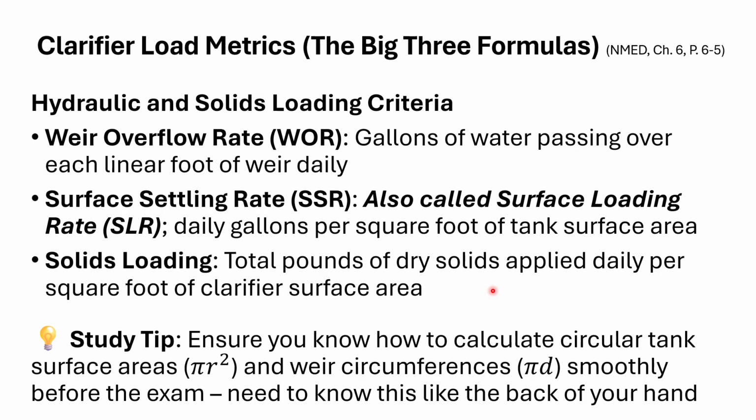So a note here, a study tip, we're dealing quite a bit with circular clarifiers. Matter of fact, that's typically what you're mainly tested on. You can occasionally and will occasionally see a rectangular clarifier, but to get the surface area of that, that's just length times width. That's pretty straightforward.